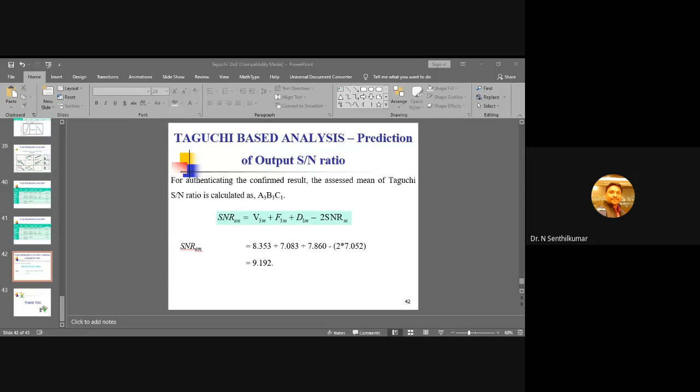For example, MRR, I am going to provide 0.25, 25% weightage. Surface roughness, 25% weightage. And the remaining 50% is given to flank wear. Put together, 100%. So that we call the combined objective, or whatever name you can call it by.